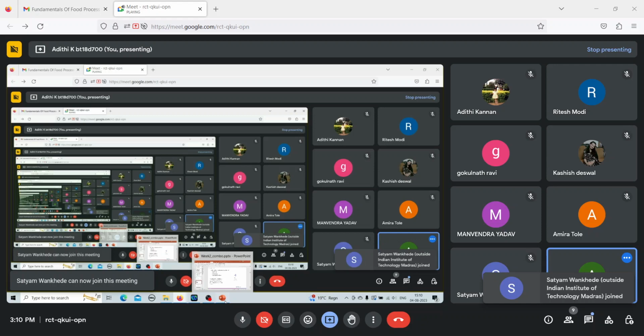This is known as the relaxation. You're measuring the stress relaxation at a constant strain. So this is the stress relaxation test, one of the tests used for viscoelastic behavior. We already discussed what the dynamic test is in one of the previous slides, where you have a sinusoidal nature. This is the other test, the stress relaxation test. Strain is constant, stress keeps relaxing, and you're measuring the relaxation of the stress.